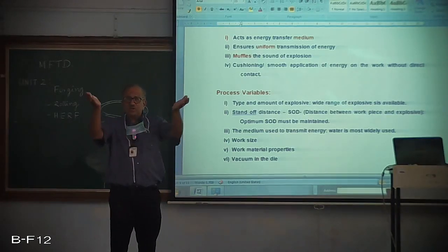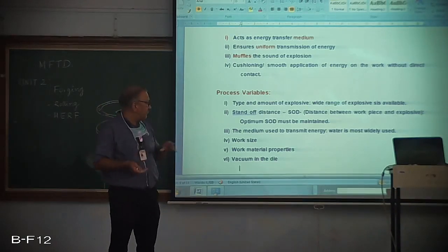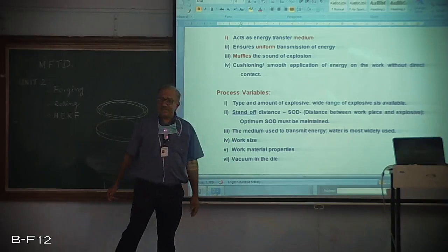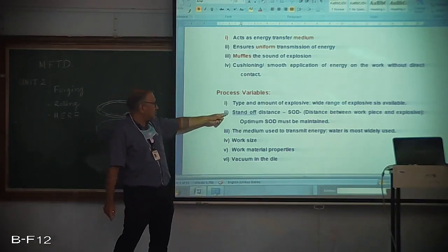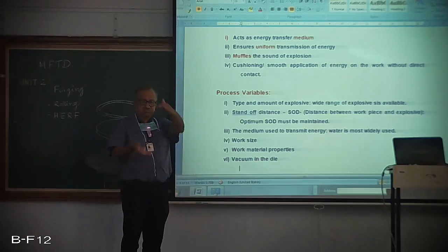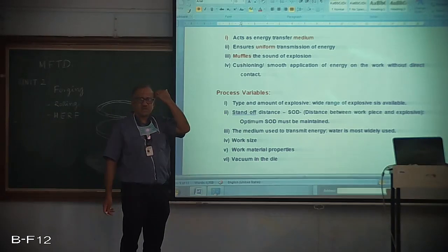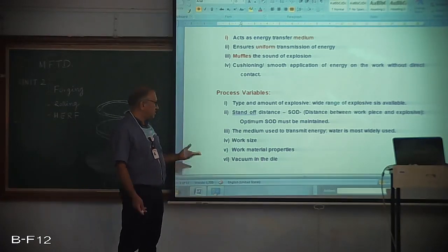We prefer uniform deformation whenever we are talking of deformation. So if the standoff distance maintained is less than optimum, then there is a problem of non-uniform application of energy, and hence some problem in attaining the required finish and the tolerances.